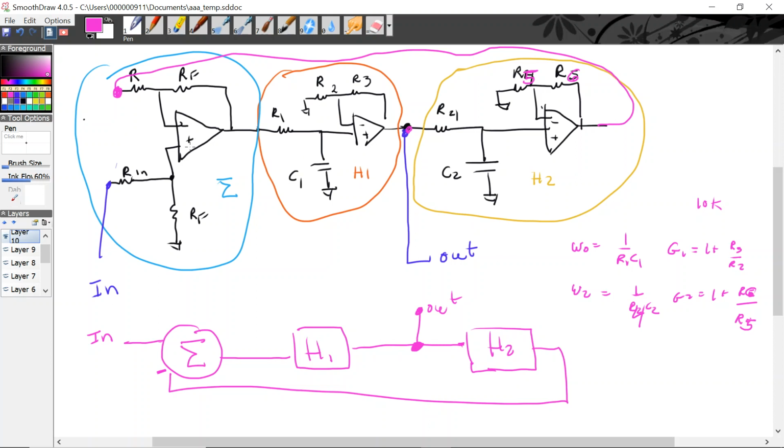I'm not going to get into it here, but that's a good place to start. If you can avoid it, don't go below 2K. As you look at the gain bandwidth, the open loop gain on these gets smaller when you have a load resistance of 2K.